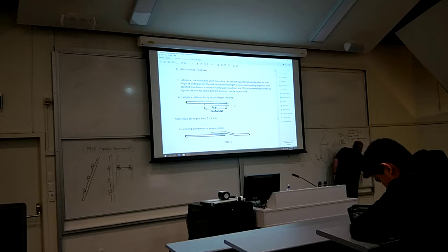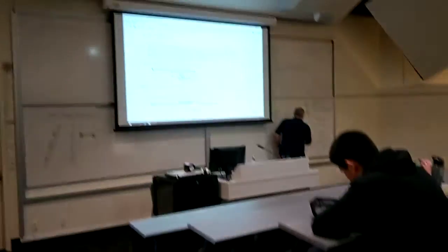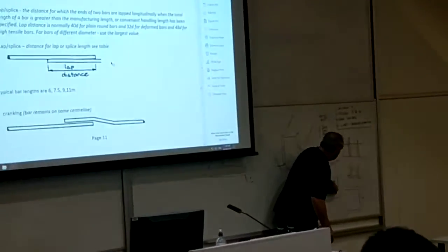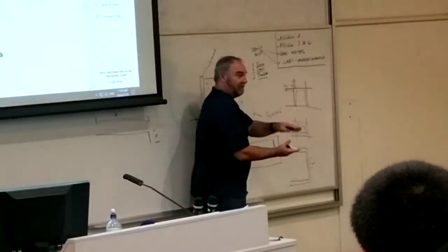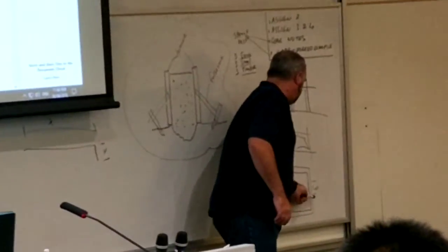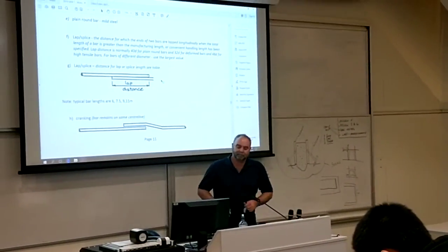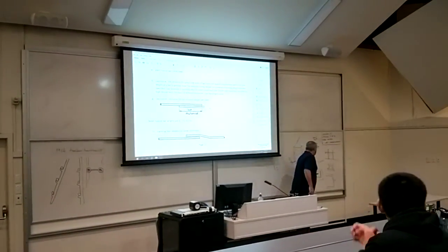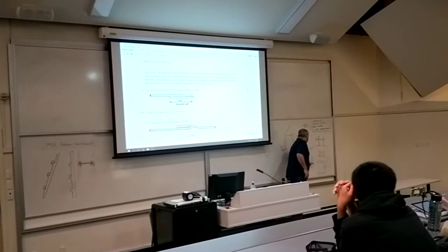However, if it is a very large end to a piece of reinforcing and your lap required is only that much, then that's your lap there. So in this case, this bar here will come along and go in there, but that is classed as the lap. Even although that might be under the sides, you're not taking the bar back in the other direction. However, if it's a large distance, then you only do the overlap for the amount that's required. You've got this situation in your assignment, so you only need to take the lap as being the minimum distance from there to there.